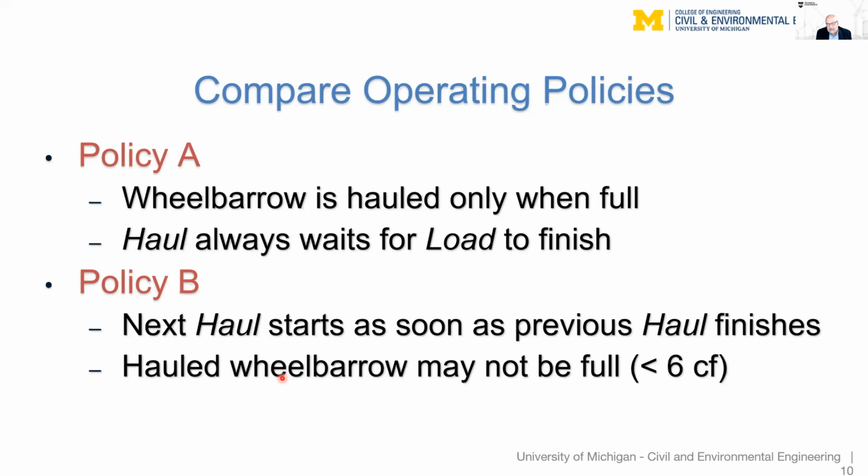As soon as activity haul finishes, the hauler, the laborer who hauls, grabs the wheelbarrow that's being loaded, irrespective of whether it's filled up or not, and starts hauling it again. In which case, of course, the hauled wheelbarrow may not be full. Its soil in it may be less than 6 cubic feet. And the question here is, well, which policy is better, policy A or policy B?